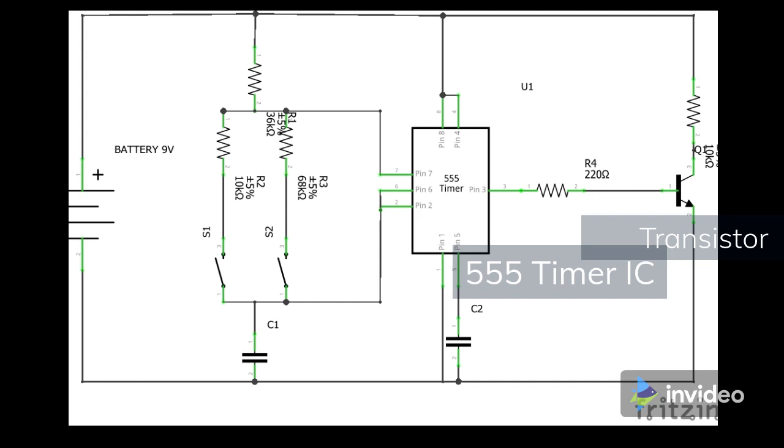The wired NE 555 timer IC generates accurate oscillation and time delays. We connect switches at the trigger and threshold pins. So when we apply the voltage supply and press any switch, the IC gets triggered and the threshold pin compares the applied voltage with the reference voltage of 2/3 VCC.